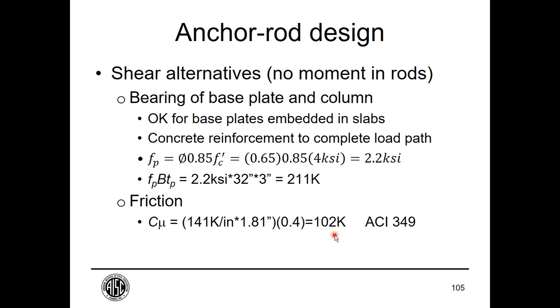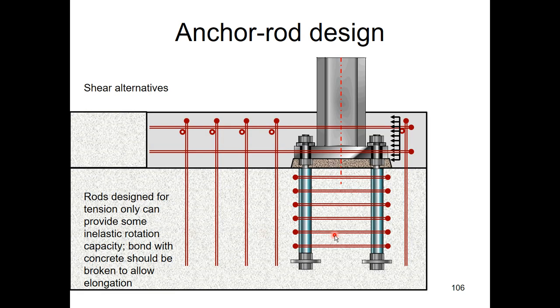You could also weld things to the base plate and drag them out. If you are using bearing, you almost always face a condition where you're at the edge of the building and you have to make sure that you have a load path for taking that shear out at the edge of the building. Say if it's bearing, you need to drag it back somehow into your slab and foundation in some detail that might look a little like this.